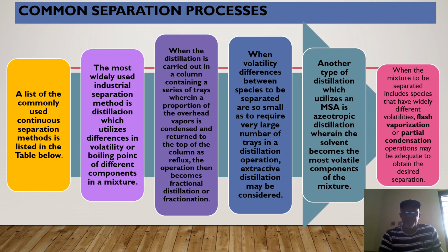Now, common separation processes. A list of the commonly used continuous separation methods is shown in the table below. We'll look at that table in the next slide. The most widely used industrial separation method is distillation, which utilizes differences in volatility or boiling point of different components